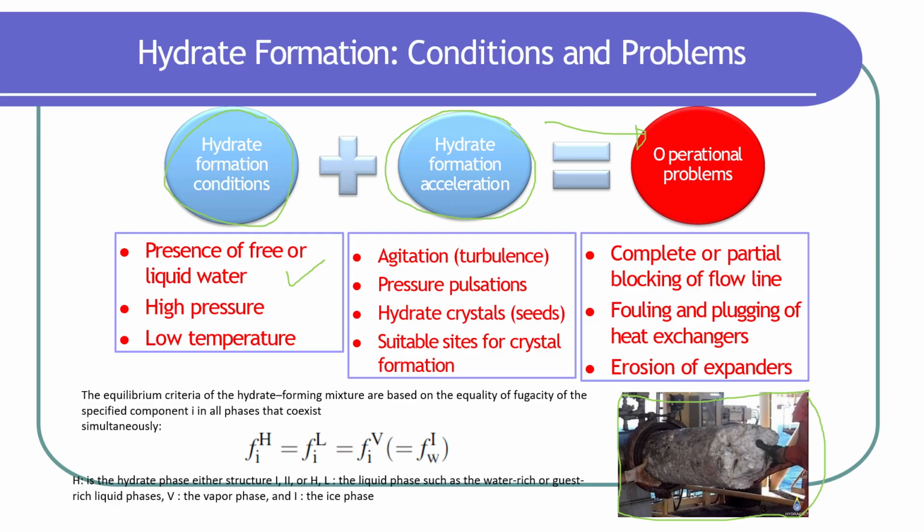That's why, when we get to chapter 6, we will talk about gas dehydration, and why it's important to do gas dehydration to avoid the formation of the hydrate. The presence of water as a liquid phase is very important to form the hydrate. Even water in the vapor phase will also contribute to hydrate formation, but not as much as liquid water.